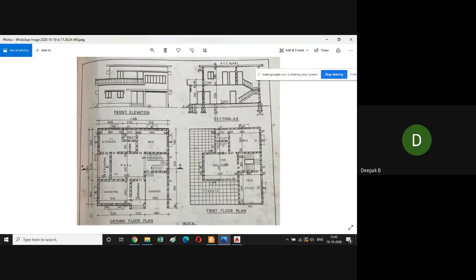Draw the projection lines upwards. As you can see, there is the plinth foundation. It has an offset of 5 centimeter. So in order to get the proper dimensions in, it should be exactly at the top or above the floor plans. So just draw the upward lines from whatever points that you see. As you can see, there is the door here, there is the stairs here, steps here. You just draw a line directly from here to this level so that you can draw the elevation.